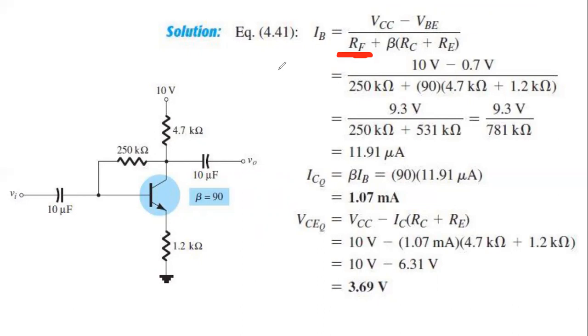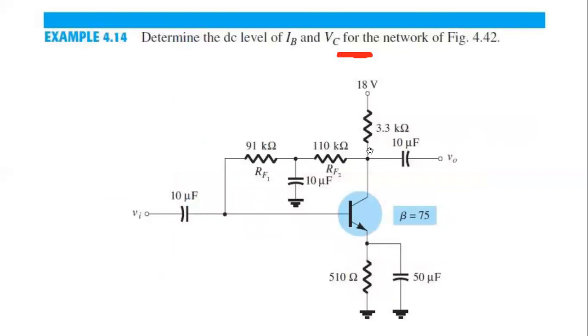If they're connected in parallel, at that time you can easily make the parallel into one equivalent resistance. In series we can sum them; in parallel you can definitely use the parallel equivalent resistance, 1 by R1 plus 1 by R2. That's true.